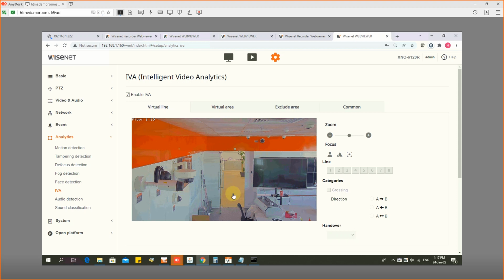So you can draw a line and you can give the line direction. If someone is coming, click on it, it will change direction. Out to in. If someone is entering your property, I need an alarm. They may be digging outside, I don't care. Maybe if it matters, then you have to put a different analytic. If they're crossing the zone, if you need an alarm, you can trigger. So here, as long as he's outside, for me there is no alarm. My this box did not become red, right? It is detecting an object, but it will not trigger an alarm. So you can even customize this line.